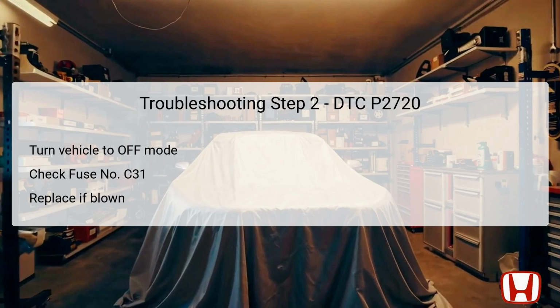However, if the fuse is blown, it should be replaced with a new one, and then the system should be rechecked. If the newly installed fuse blows again, further investigation is needed to identify any potential short-circuit issues affecting the fuse circuit, which will involve tracing wiring continuity and checking for ground faults. A proper diagnosis at this step can prevent further complications down the line.